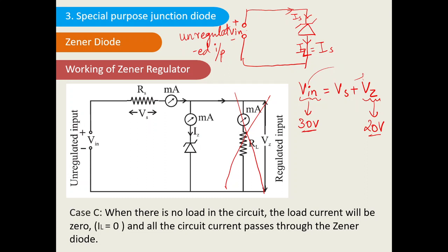And the corresponding Zener diode will be damaged, right? So what we are doing is applying a resistor over here. This is the source resistance. It will introduce a new voltage Vs, so it will drop 10 volts across it. This Rs will drop 10 volts across it, such that it protects the Zener diode from going towards 30 volts.